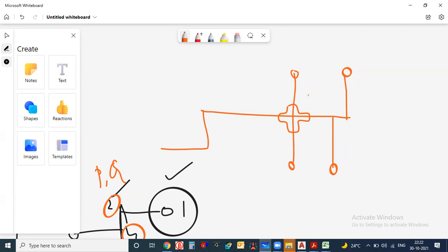So there may be chances that there is a loss of pressure, or in some places if the pressure is good, you can go with the 4-way or cross fitting also. But I think it will affect our hydraulic calculation. Sometimes we cannot get the proper results. So that's why I usually avoid this kind of situation, the 4-way. It's better to go with only 3-ways. If you're going with 3-way, you can get the proper nodes.